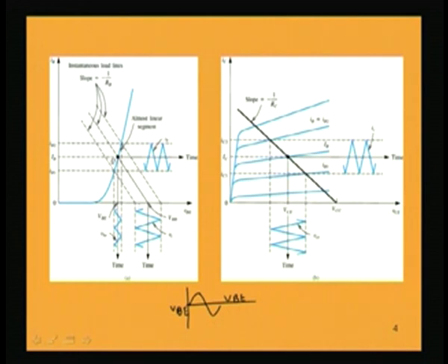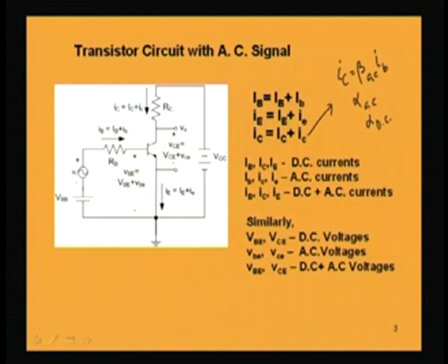Now, in the input circuit the DC load line can be drawn by connecting the maximum and minimum values on the x and y axis, for a particular RB, because if we change the value of RB our load line will differ.